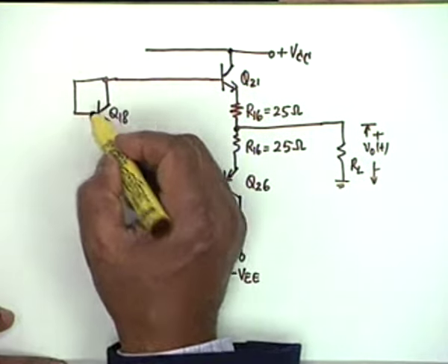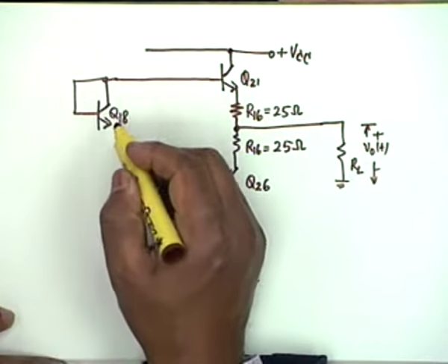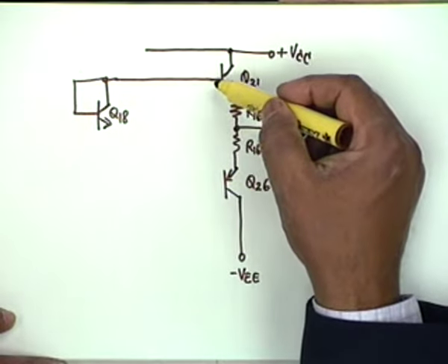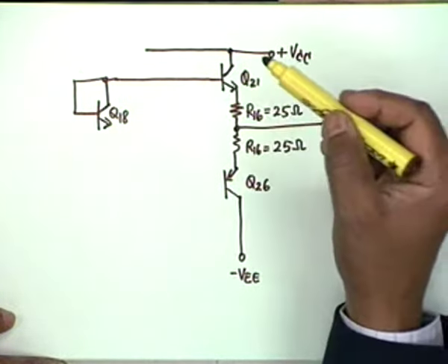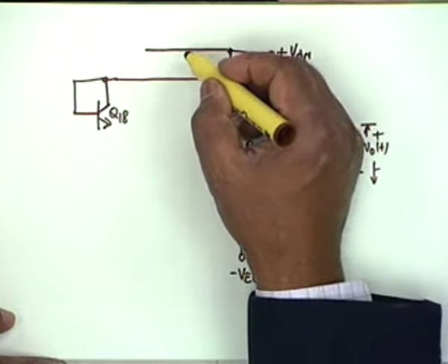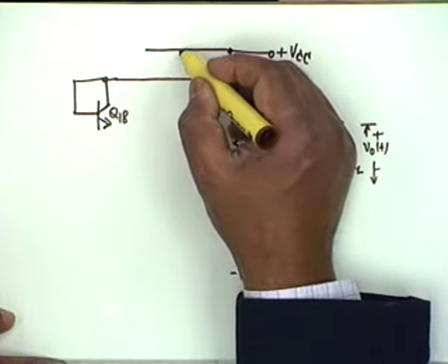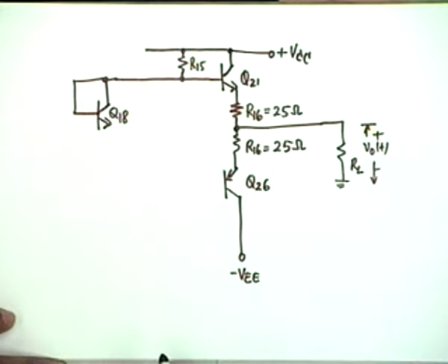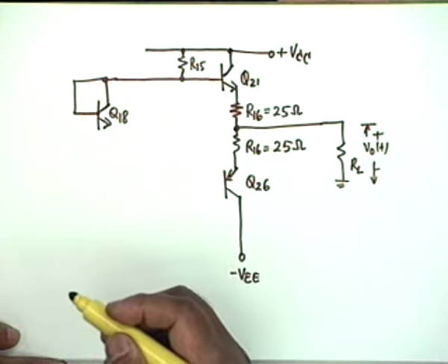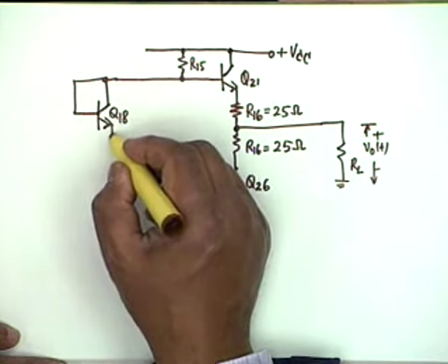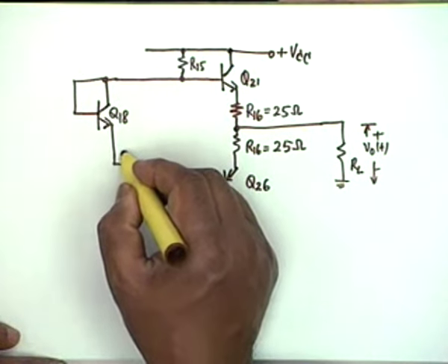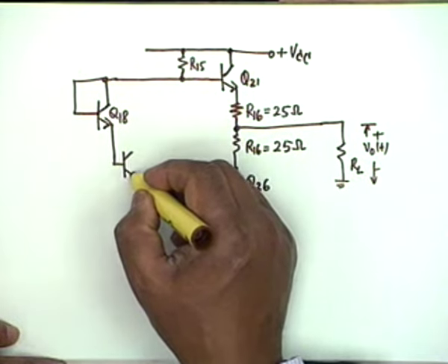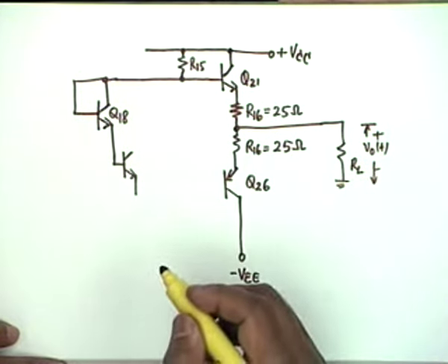These numbers are there because there are other transistors which you are not drawing. Okay. This is a diode connected transistor, but not from here. It is from this base. Okay. And in order to drive a current through this, we require a resistor. We require a resistance from here, which is R15. Okay. Then we require another such diode connected transistor, but for reasons of the overall mu A 725 design, it is connected like this. It is not connected as a diode, it is connected like this.